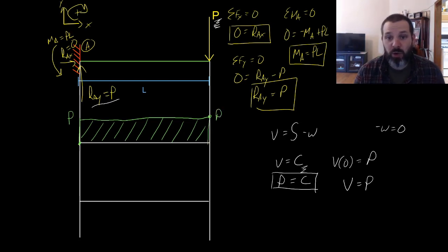Your shear and moment diagram must always begin and end at 0 because they're in equilibrium. When you have point reactions and loads, what those point reactions and loads do is they cause your shear diagram to jump. Loads cause your shear diagram to move, shear will cause your moment diagram to move.